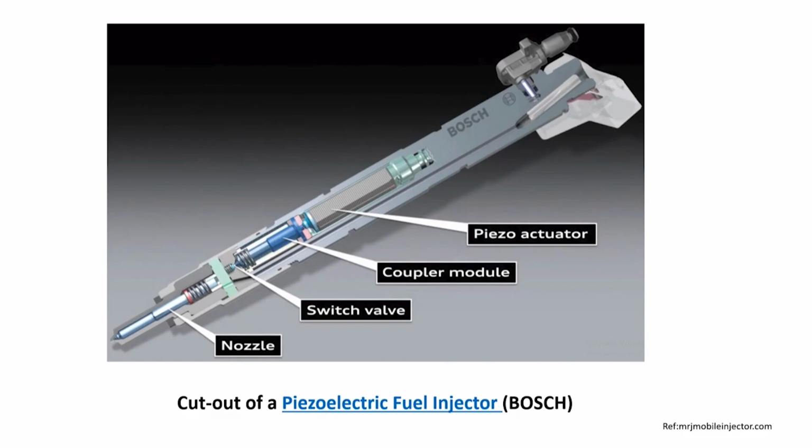I will show you one particular example of this, the piezoelectric fuel injector, like the Bosch piezoelectric fuel injector. You can see here there are so many piezoelectric stacks stacked one after the other, right. I am just showing you very broadly. So, now what happens if you apply a voltage, you will get a large force generated, and this large force will control a switch valve, and that switch valve, once it is open, then the fuel will be injected into the system. And because of the very high bandwidth, that means very fast response time, you will get to inject the fuel at the proper moment.